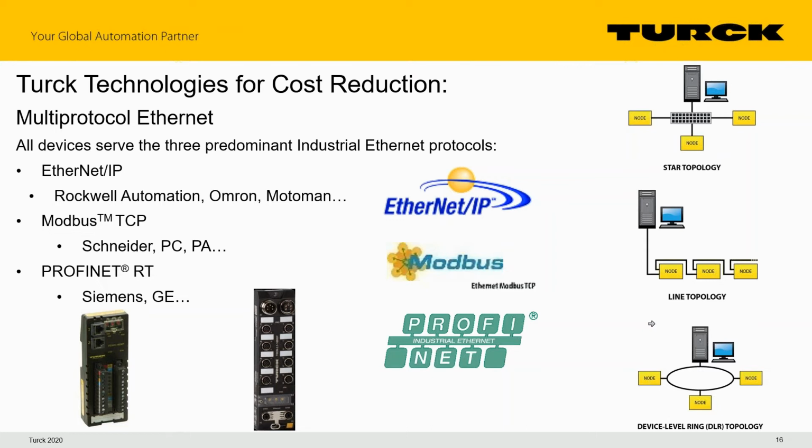And along those lines, if you have really long distances, I've done pumping stations that were 7 miles away. You can run fiber or you can do an Ethernet radio. Either one of those is suitable to be that link between nodes. We also support what is known as device level ring, DLR, topology. We are a certified slave for both Rockwell and Siemens. That is really the key, is the master that you need to run that.